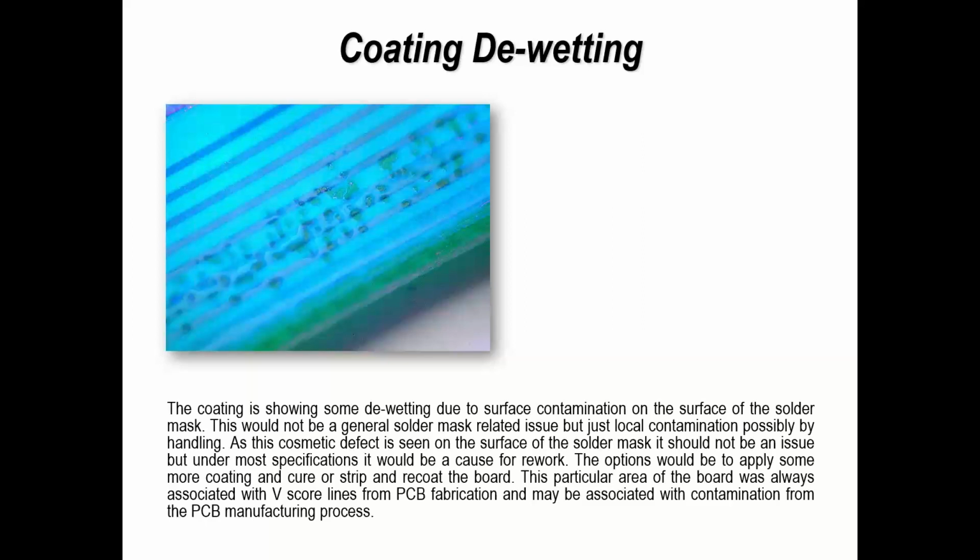We put it through reflow soldering, we put it through wave soldering, we put it through selective soldering. So lots of different processes which could contaminate or change the state of the board. So again, it's being aware at what step that change in the surface impacts your coating. So again, it's experimentation. There's no rule book. It's just looking through your process to see what might have affected it.